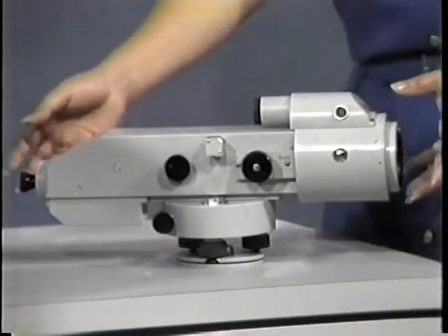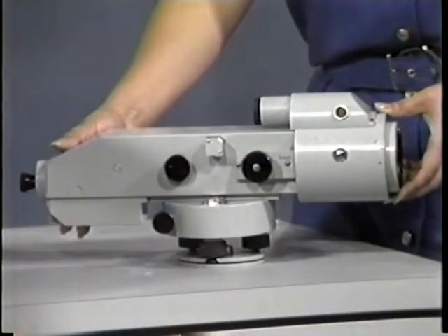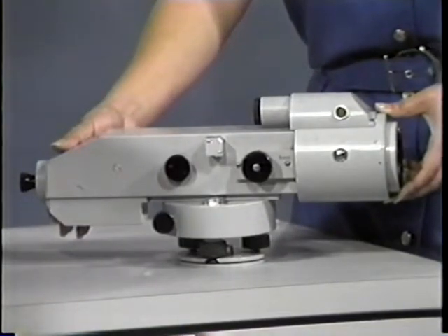In first order work, the levels used are highly accurate micrometer type pendulum levels such as a Zeiss NI1, and single construction INVAR yard or meter rods. Carol has an NI1 level and first order rod to show us. This is a Zeiss NI1 pendulum level.